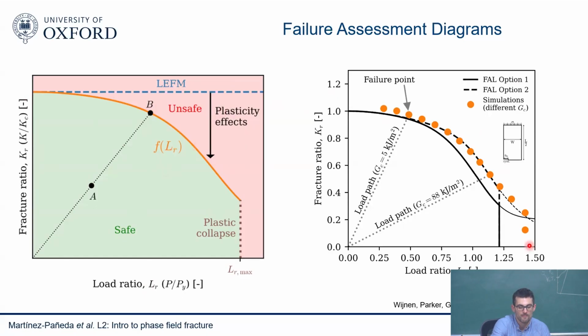What we do here is we run simulations where we increase your load. We start here, of course, at the beginning, load 0, our stress intensity factor is 0, our toughness is 0. But as we start increasing, then depending on what crack size we have or what toughness we have, we go through one path or the other, and then eventually we see failure.